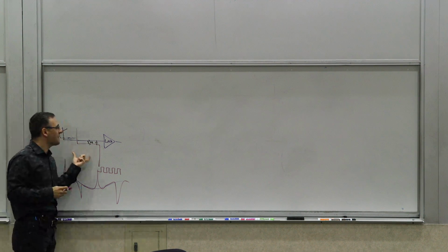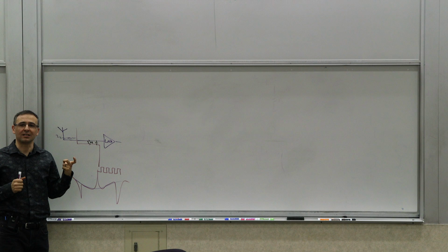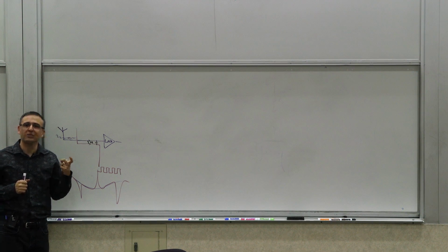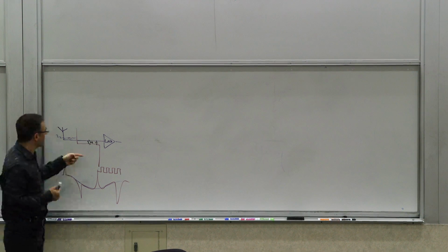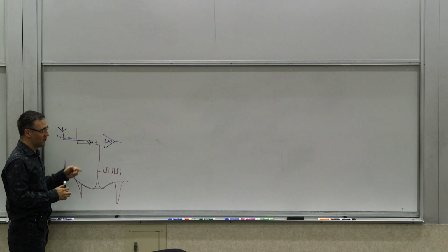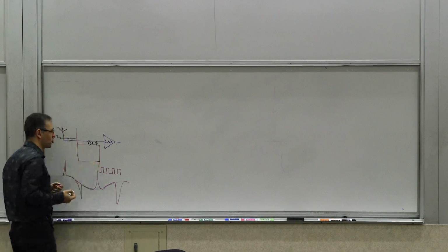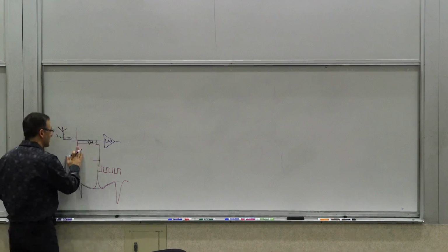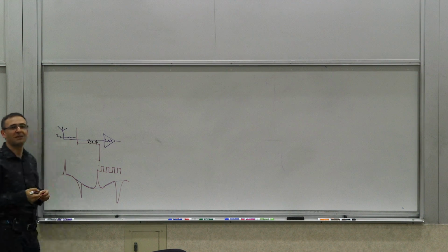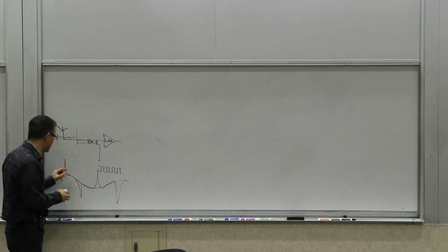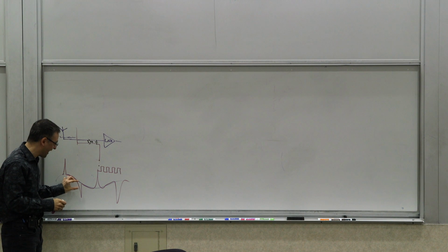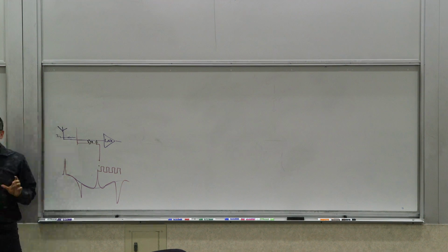So now, think about it. How can we reduce our sensitivity to the signal? And how can we reduce the impact of the source? One of the things you can say is, well, don't draw this line here. Draw it farther away. Sure. It would reduce the coupling a little bit, but it won't eliminate it. And if you have something that's quite sensitive, yes, these spikes may not be this large, they may become half as large, but still they're large.